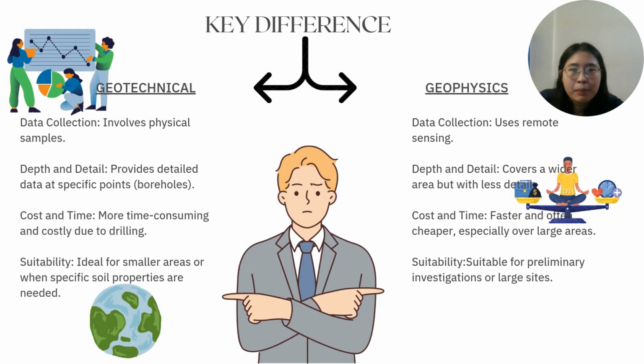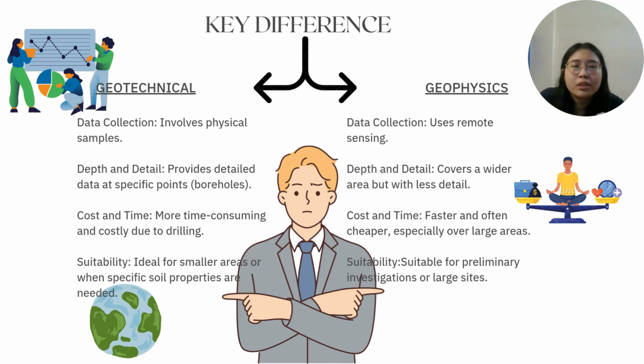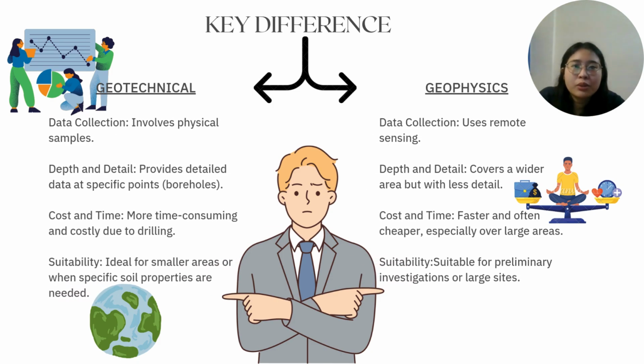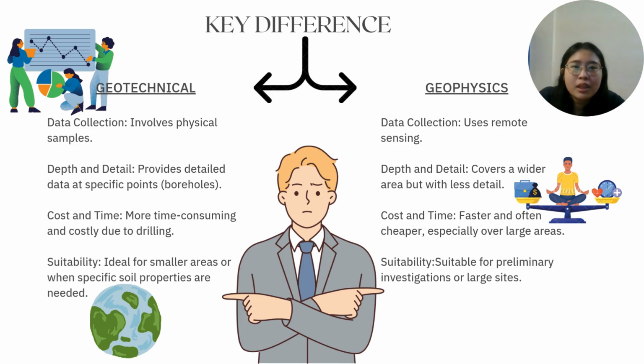Now people might be wondering what the difference is between geotechnical and geophysical methods, because both are used to detect the soil properties and the soil profile under the ground. Let's look at geotechnical first. In terms of data collection, geotechnical work needs physical samples, and it provides detailed data at specific points, which means the more boreholes we take, the more detailed data we can get.